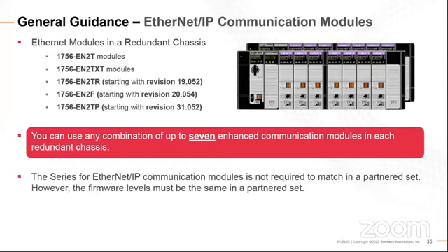It may require changing how the network is designed, especially when we're going from ControlNet to something like EtherNet/IP. So in those instances, just get with us. I'm a huge fan of napkin note drawings to review what you guys are going through. In terms of general guidance for ControlLogix redundancy as we see fit.